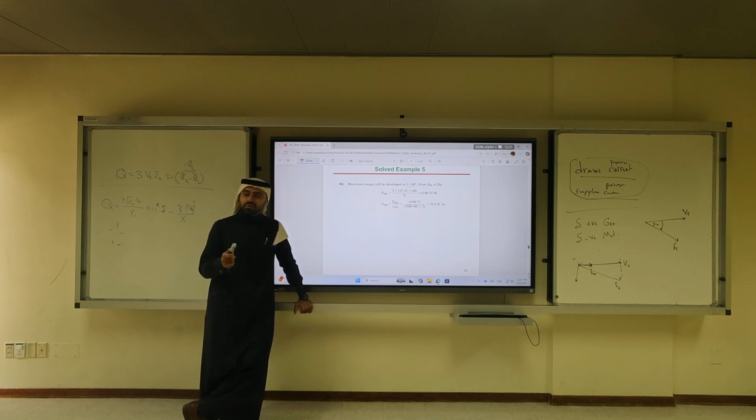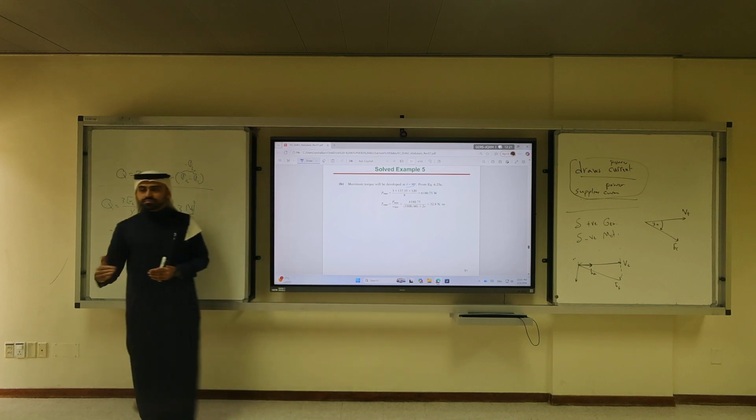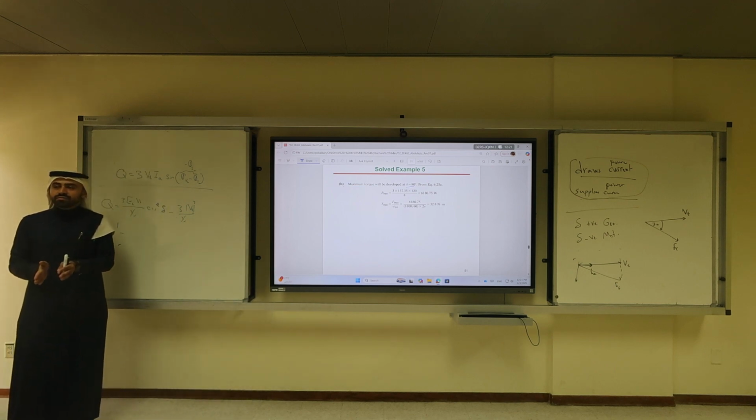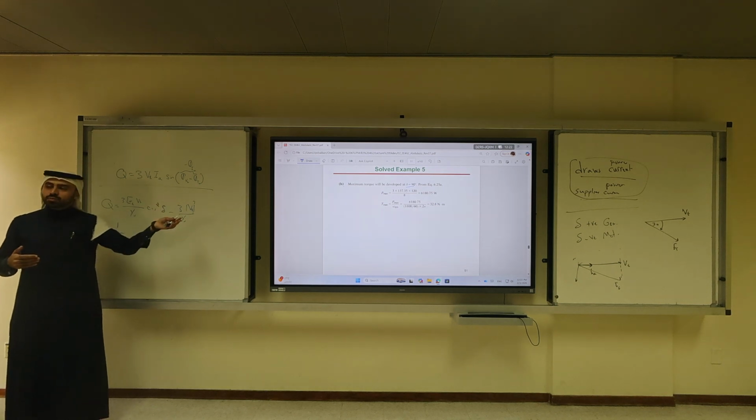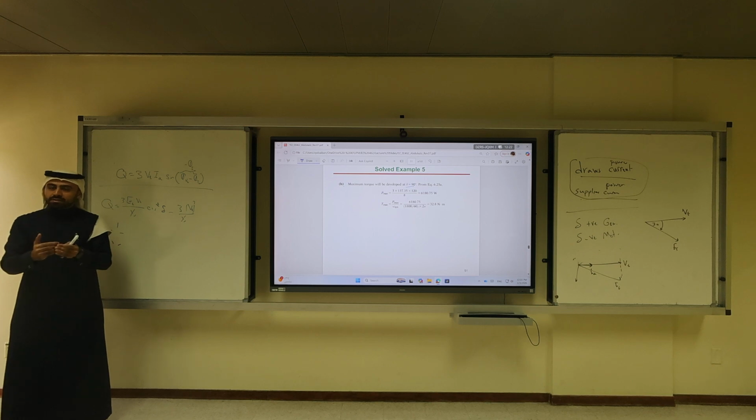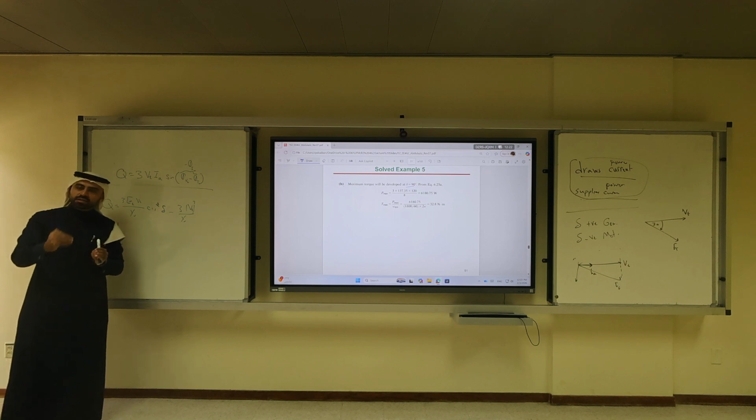In electric golf cars, I remember this when I was working with one of the manufacturers for EVs, by law in the United States, they are not allowed to increase the speed. A golf car cannot drive 100 kilometers. But can the electric motor drive 100? Yes, so they cap it. One way to cap it is to use the inverter not to exceed a certain torque angle.